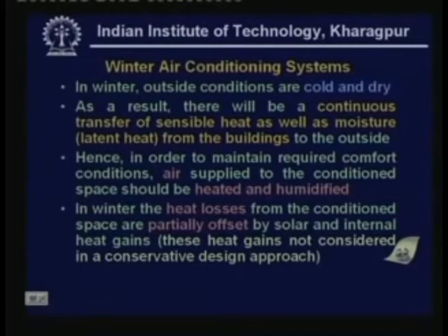Another difference between summer and winter is that in winter the heat losses from the conditioned space are partially offset by solar and internal heat gains. The solar energy actually adds heat to the building, and internal heat gains also add heat to the building. So, it partially offsets the heat losses from the building. In a conservative approach, these heat gains are not at all considered in the design. You assume that there is no internal heat gain and no solar heat gain, and you arrive at the required system capacity. So, this is a conservative design approach as far as winter air conditioning systems are concerned.